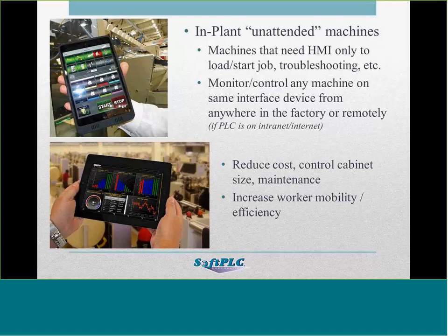So why have the HMI there? It adds cost, it adds complexity. Someone could just come by with a tablet or a laptop, access the IoTView screens, do what they need to do, and then disconnect and go on to the next one. So this is a nice solution, like I said, for certain types of machines.